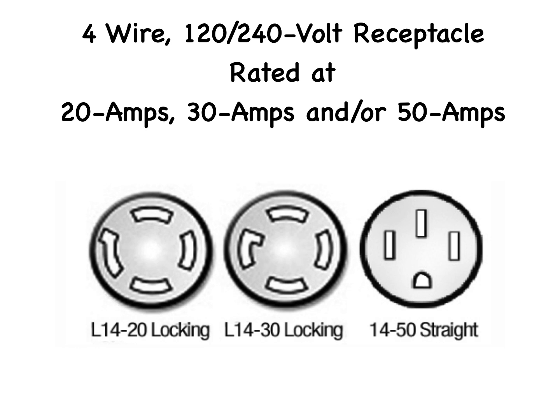Furthermore, you can purchase or use a generator of any size, provided the generator is equipped with a 4-wire 120-240 volt receptacle rated at 20 amps, 30 amps and or 50 amps. This will allow you to easily connect to your existing power panel and is designed to be compatible with 20 amp, 30 amp, and 50 amp connectors. Check your generator for one of these receptacles. These receptacles are rated for 120-240 volt output, which is what you'll need to run your home.